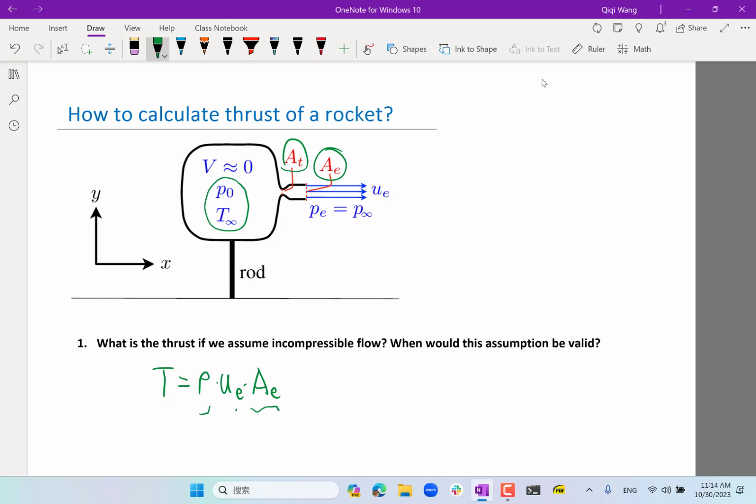Based on the pressure gradient, that's right, based on pressure, but specifically how? Using the isentropic flow pressure ratio equation with the Mach number. Yeah, so here it's actually simpler. We are saying, what if we have incompressible flow? What you said is the correct thing to use when we get to compressible flow. Is there something even simpler to use for incompressible flow? By the way, we are also assuming inviscid flow for the entire problem.